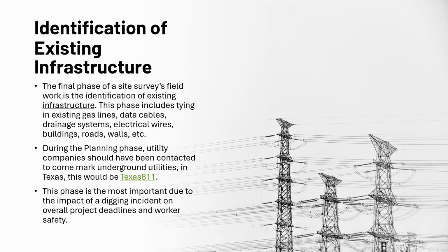We'll talk a little bit about that "reasonably" standard later as part of our survey report, because we're going to take a deep dive into that. But again, do not devalue the importance of identifying existing infrastructure. It's not just, okay, there's a house here, let's shoot the sides. Oh, there's an old slab, but what is underground? Why aren't we seeing utilities?